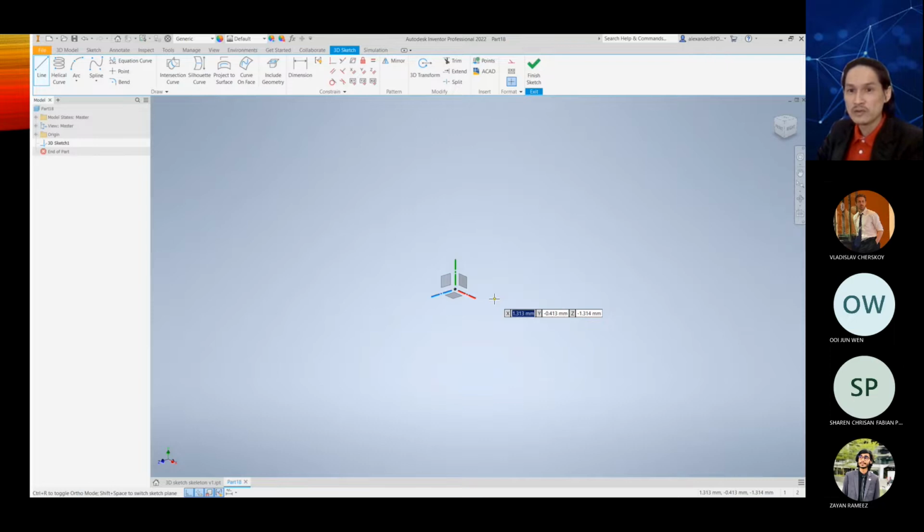So if you want to generate a frame, 3D sketch is a must as the starting point. We are doing the 3D sketch to prepare for the frame generator, or to generate the frame in Inventor. I know other CAD software also have 3D sketch for their own purposes, but here it will be for the frame generator.